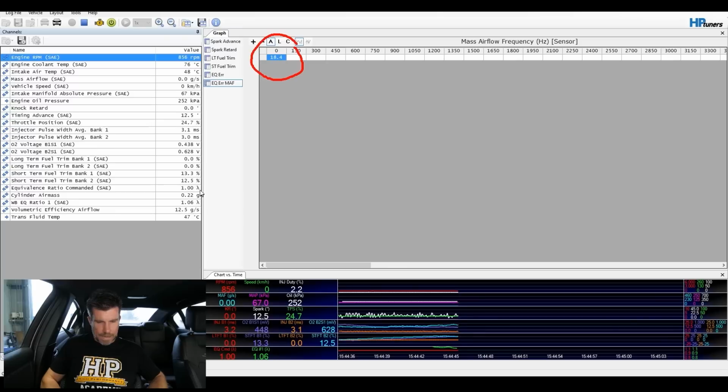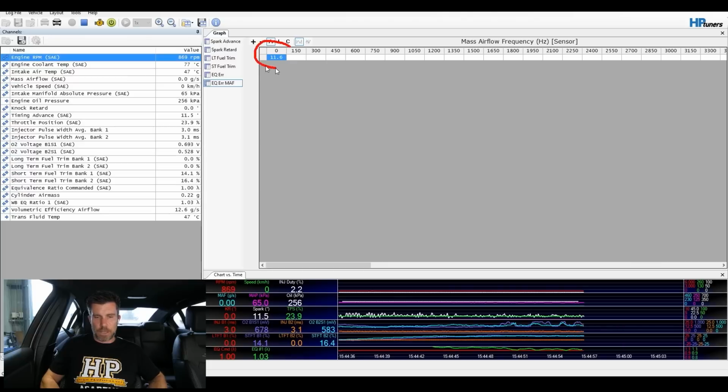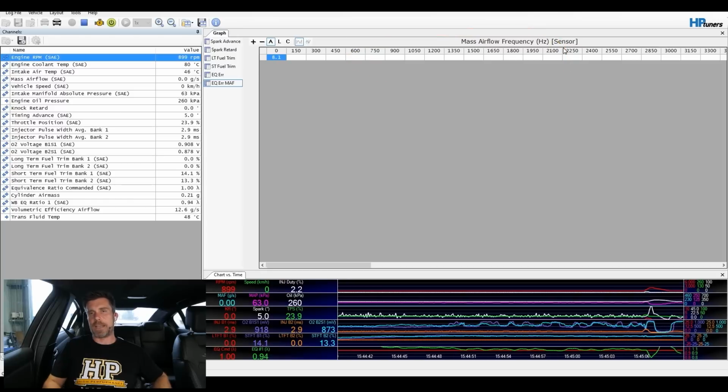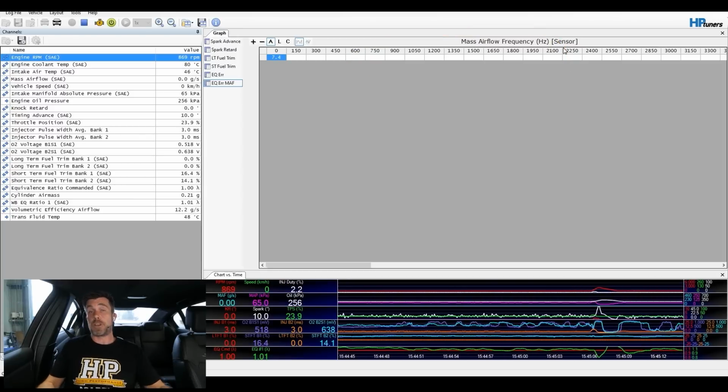We can see that our air fuel ratio being measured at the moment is sitting at 1.09, so we do have an error there. As everything warms up, that's going to come down, and you can see that value slowly but surely started up in the 20s. Now we're down at 10%. Now of course, if we did have a mass airflow sensor fitted on this car, as I blip the throttle and we moved around, we would be moving all around this table. That's not the case because we have a speed density patch applied, but essentially if you've got a mass airflow sensor, the job is done.